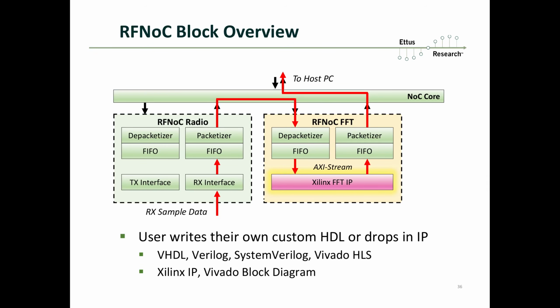There are several options for creating or supplying the user-defined IP. Users may certainly write their own custom IP in Verilog or VHDL. Users may also use IP from Xilinx, since Xilinx Vivado is used to build FPGA images. There is free open source IP available from opencores.org, as well as from Theseus cores. Many third-party companies provide libraries of IP that can be used and integrated. It is also possible to use Xilinx high-level synthesis, or HLS, to auto-generate Verilog and VHDL code from C++ source files.